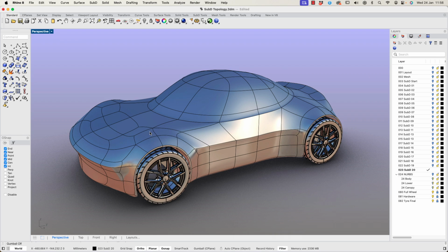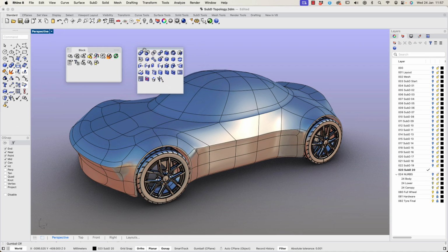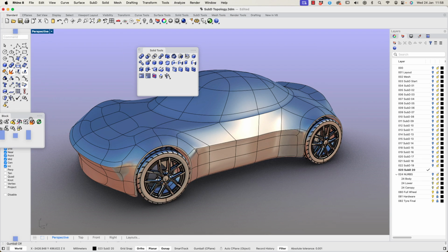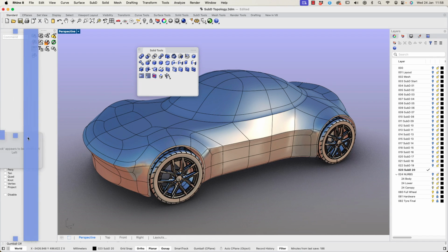It's now much easier to pop out toolbars, and, for example, any toolbar that has a grey triangle in the bottom right-hand corner can be expanded simply by holding down the left mouse button on the triangle and dragging out the toolbar. The Toolbar tab sits in what is now called a container. If I pop out another toolbar, you'll see that I can dock these containers. And when I move the container into a position where it can be docked, I'll see these blue rectangles indicating where I can place the container. So to dock on the right-hand side of the sidebar, I'll pick here.